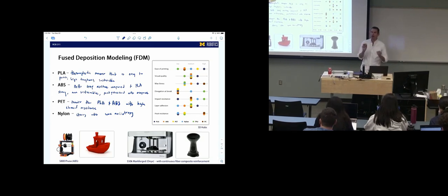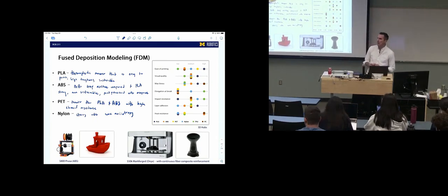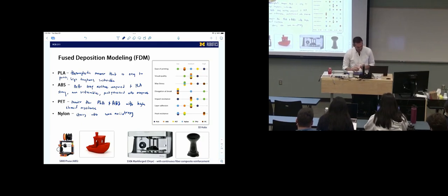Yeah, it's whether the properties of the material are consistent across dimensions. So if that's true, we would say it's isotropic. If it's non-isotropic, then its properties change with the direction. Why would 3D printers have non-isotropic properties? You're laying the filament down in one direction, in the XY plane and stacking it.